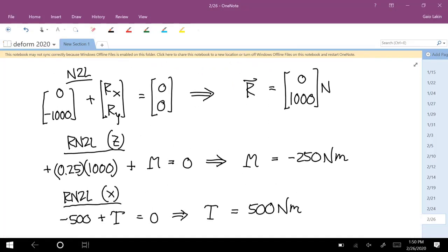But think about what would happen if we arbitrarily chose to isolate the left part and calculate the loads applied to the left by the right. We could have just as easily isolated the right and calculated the loads applied by the left. Would we have gotten the same things if we'd done that? How would it change? Just different signs. Yep, because of Newton's third law.